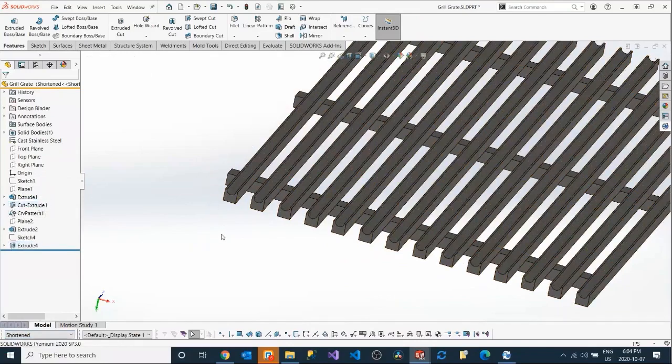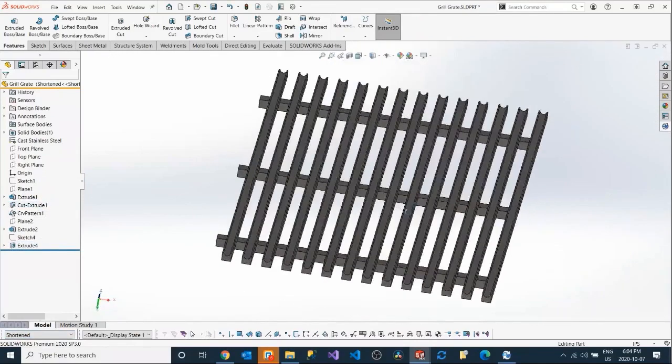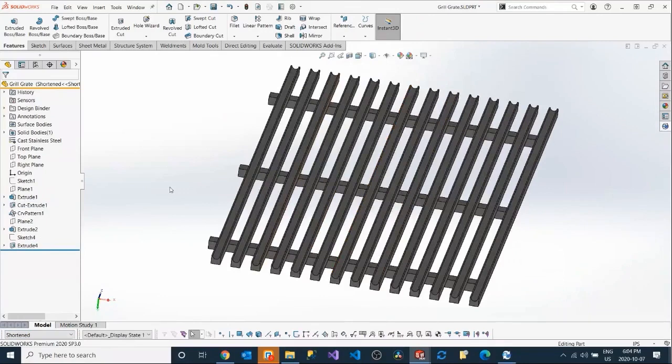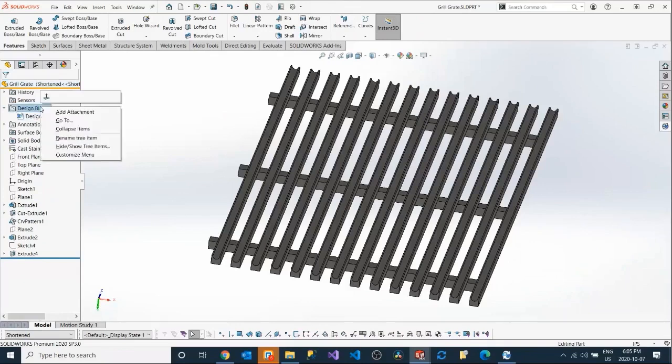So now that I've made these changes, one of the hardest things when working in SOLIDWORKS without some kind of back end is tracking your changes. And we see people lose their information often. Now, if you've ever worked in SOLIDWORKS and you've never seen the design binder, it's a folder that you can show through your system options. And right out the box, you have this embedded Word document called your design journal. You can also attach external files, like Excel spreadsheets, like calculations, all that kind of stuff. You could attach them right into this design binder.